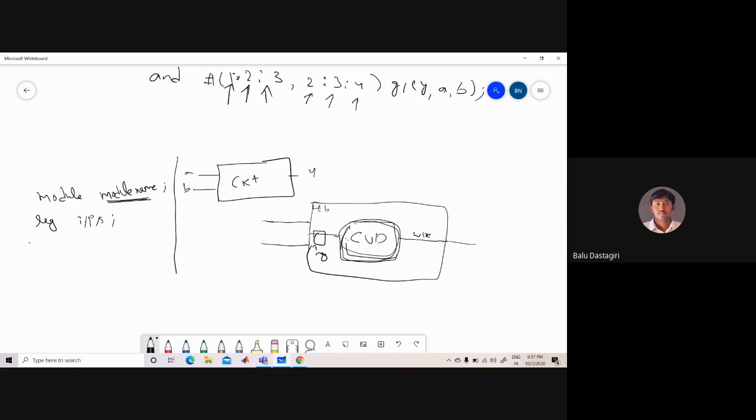Okay. Next, declare the outputs as wires. These inputs and outputs should have the same names which we have given in the designing module. After that we have to specify the test cases by using the initial or always block, with the time units. So specify the initial or always block, begin it, specify the time units, and after that end the initial or always block.